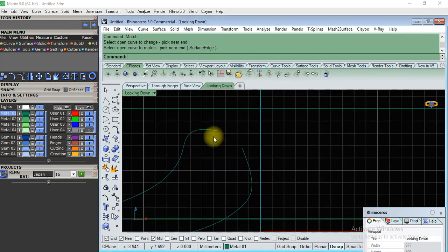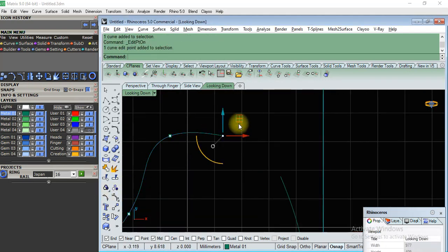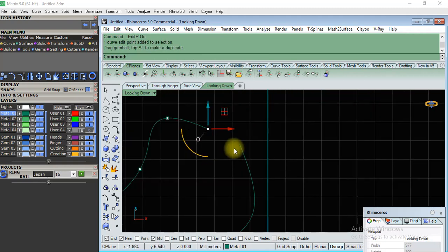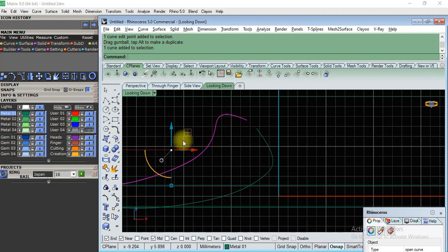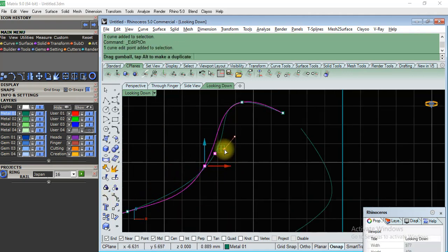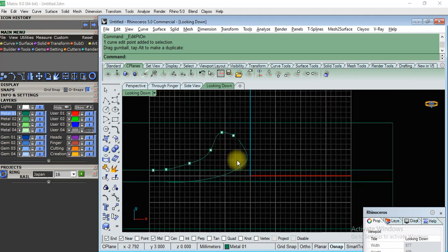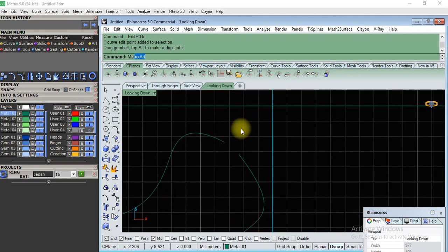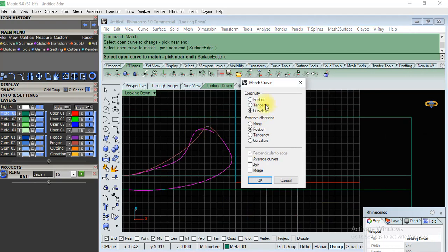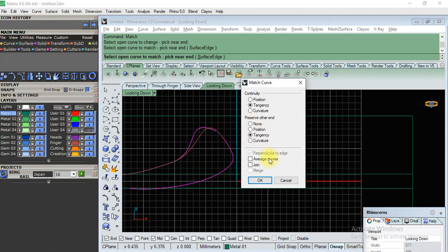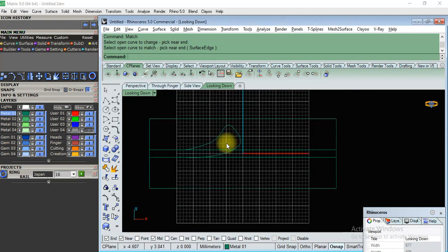So this is quite a change. Let's make a little bit more turn, because it is changing the curve's position very badly. Suppose I want this type. Now use the match command. Not matrix, but we want to use match. Select the curve, select the second curve, and use tangency and tangency. You can also click on join, so it will set the curve and change the position.